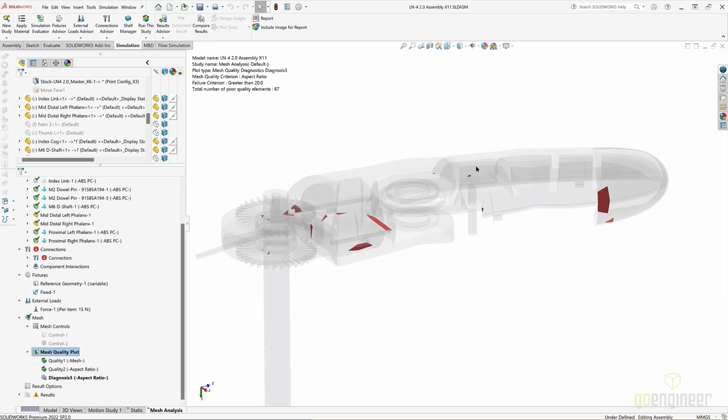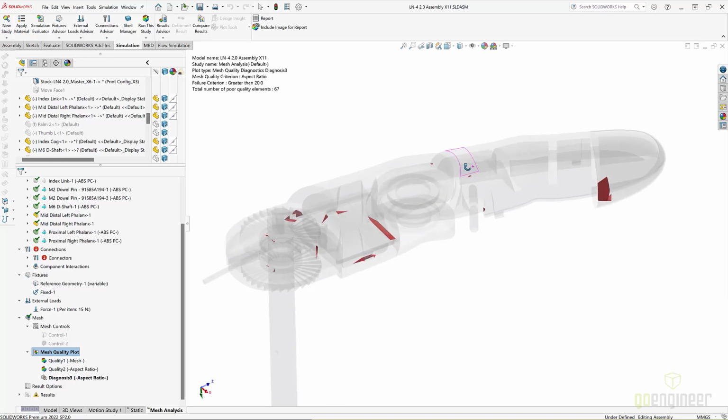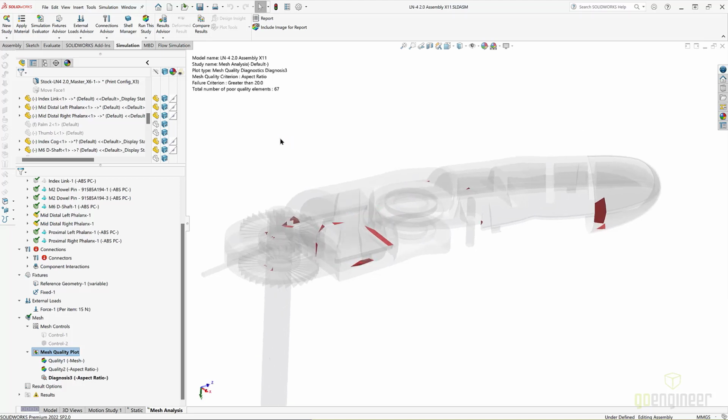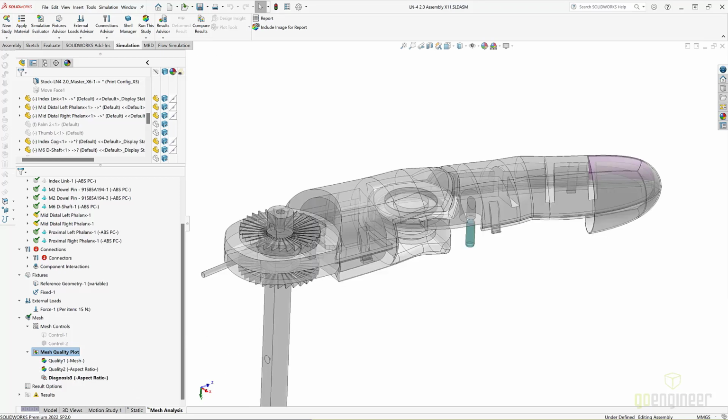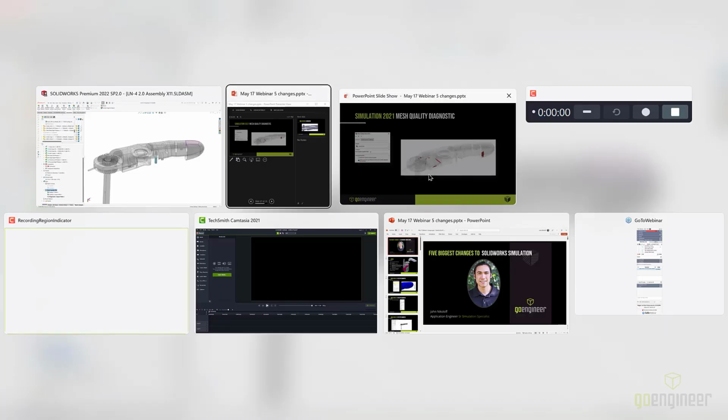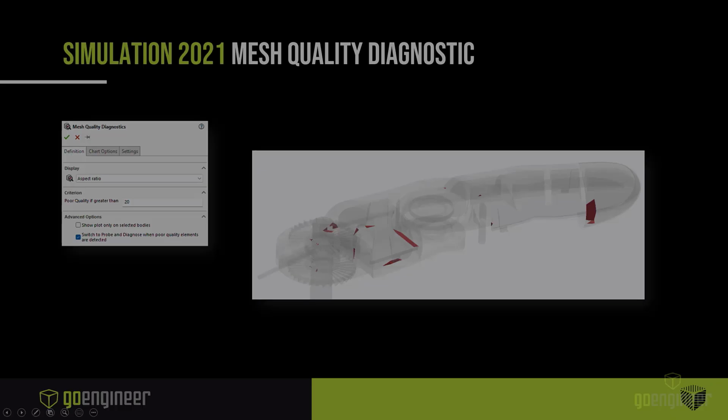And that really makes the design less accurate because we're not understanding what's happening inside those large elements. Because if we apply a mesh control there, we could increase the number of elements and nodes in that region and get a better idea of what's going on there versus having a very coarse result over that certain region. And furthermore, I really like how translucent the model becomes, so we can easily see where our elements are bad, and it just takes the guesswork out of this.